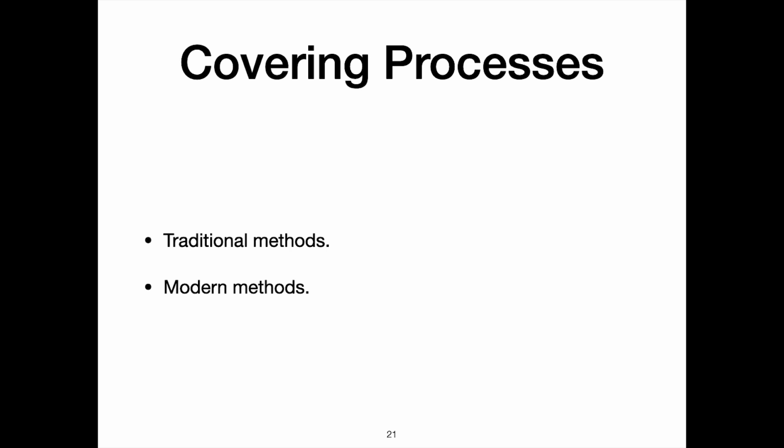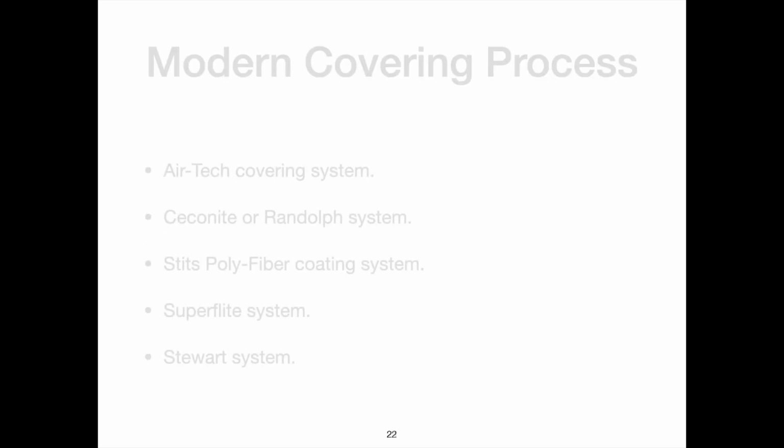The second is the modern method of covering. They follow the traditional method with minor differences. Synthetic materials are used and covering is adhered to the structure using dedicated glues. With both methods of covering, it is normal for the aircraft to be reweighed after renewal of the fabric to determine any change in mass and center of gravity.